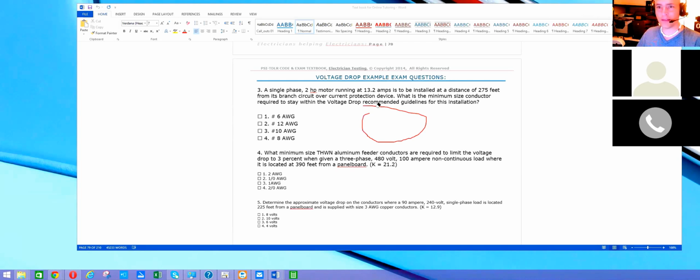So first of all, ultimately, what is this question asking me to do? I'm looking for the maximum size conductor required to stay within the voltage drop. So the wire size here is ultimately our goal. Wire size is going to be the first circle that we had, 2KID on the top. And I always have to solve for the bottom variable. That's why I'm using this one, because if I'm looking for wire size, it's 2KID over VD, circular mils on the bottom down here. So I'm looking for this right here. This is my question mark, my unknown value. Voltage drop is right there.